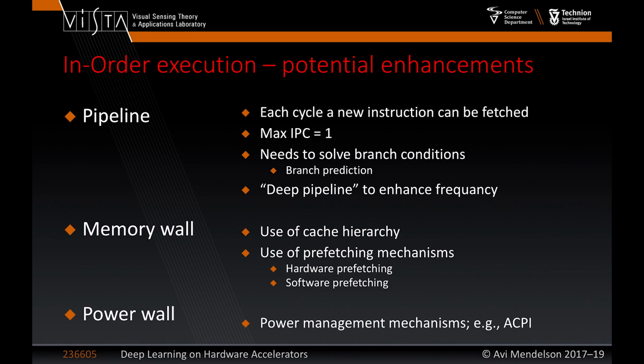I will not go into all the details, but the idea of the pipeline is that now, instead of waiting 5 cycles, every cycle something is finishing. And since every cycle something is finishing, the throughput of the system is 1 instruction per cycle. You ignore the filling up of the pipeline, but in general, if we put in more pipeline stages, we can even accelerate the clock rate.